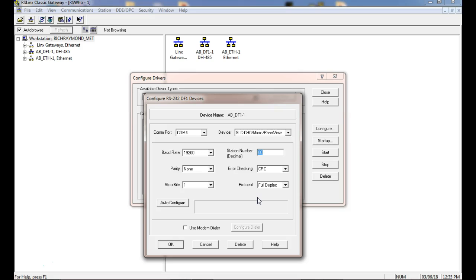Yeah, and it's kind of misleading. Originally, it was the number of bits per second, and it's still true on the old RS-232 interface, which is what this is. So this means right now, and this is the fastest speed that RS-232 supported, 19.2, or 19,200 bits per second.